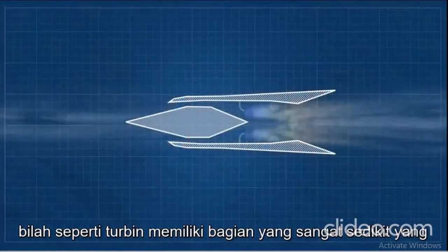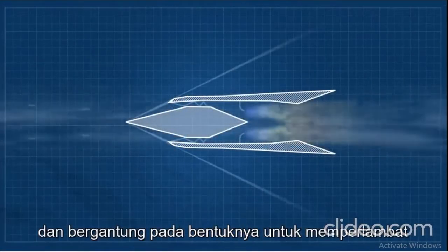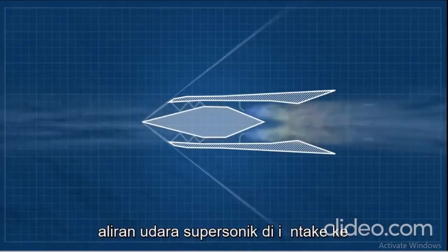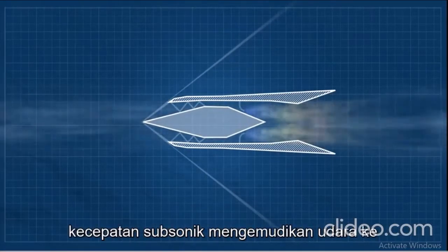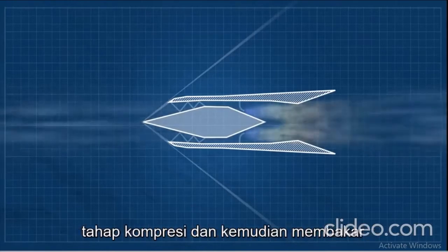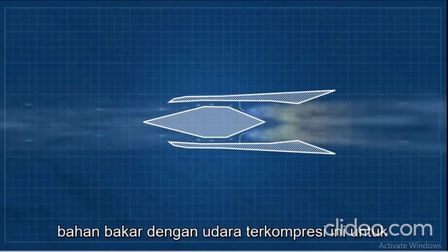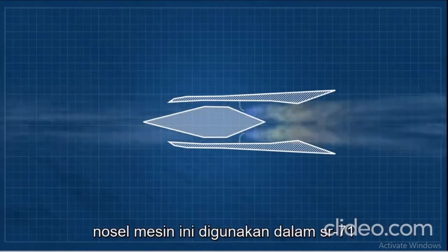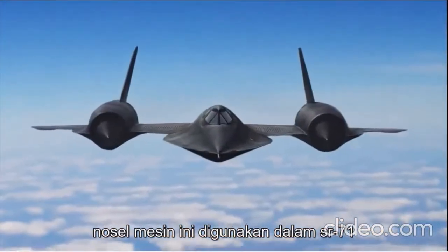It has very few moving parts, and it relies on its shape to slow down the supersonic airflow at the intake to a subsonic speed, driving the air to a compression stage and then burning the fuel with this compressed air to generate supersonic thrust towards the nozzle. This engine is used in the SR-71 Blackbird.